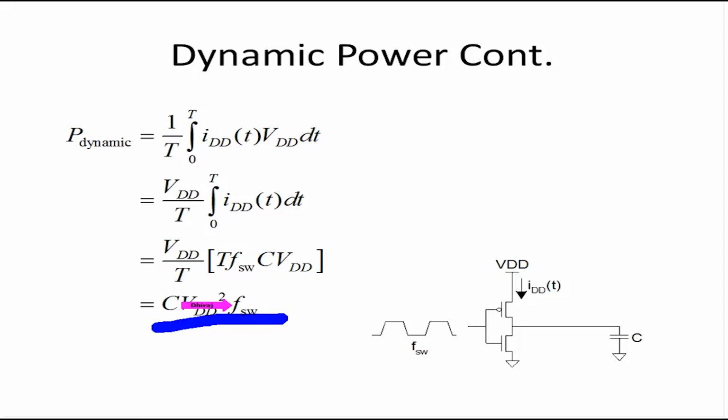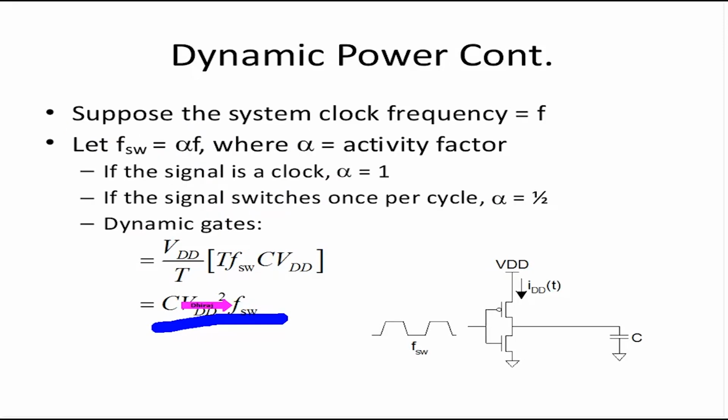What is the signal? The switching frequency of the clock is highest. It toggles twice per cycle. It goes to high, goes low. Again, the higher frequency clocks will have more switching activity compared to lower frequency clocks per unit of time. So high frequency clock networks consume most of the dynamic power. Data signals comparatively switch lower. The switching frequency of a data signal is not as high as the clock.